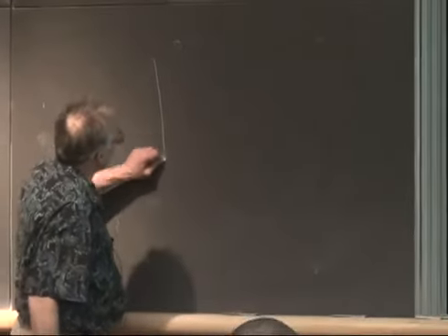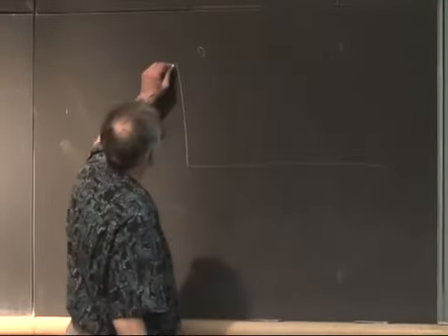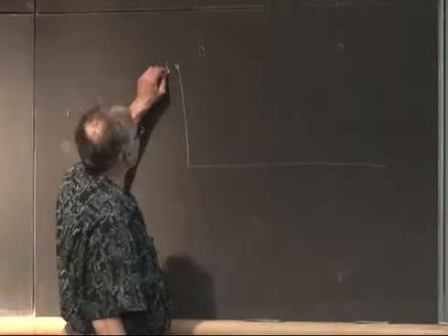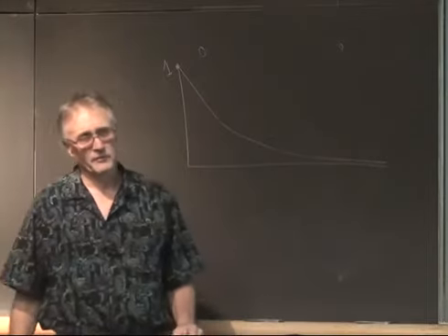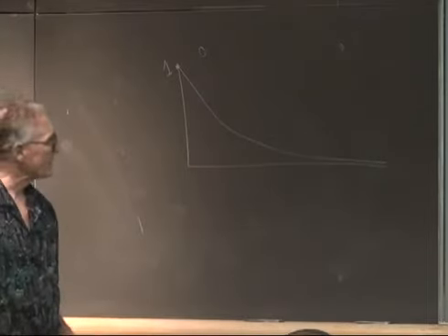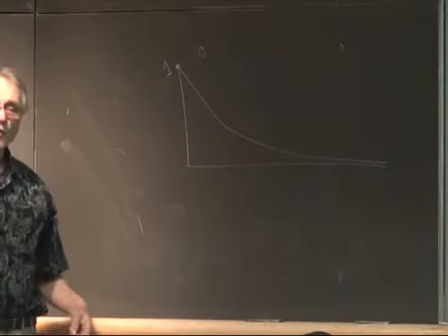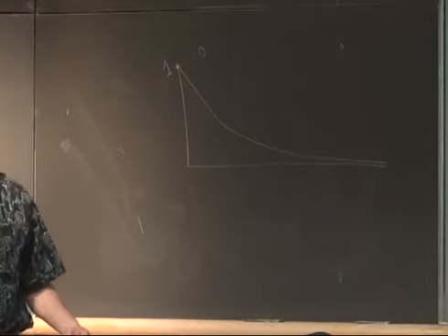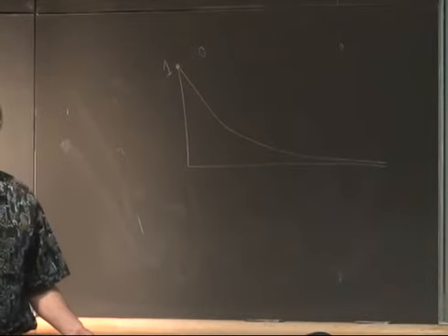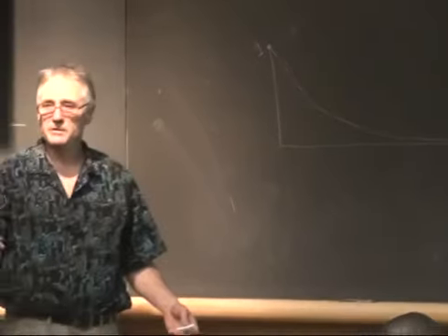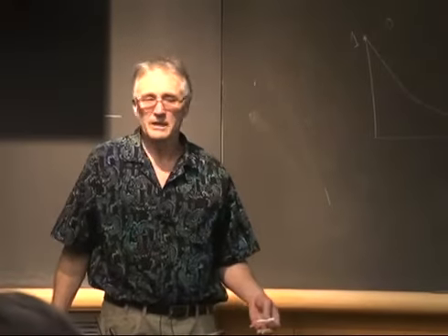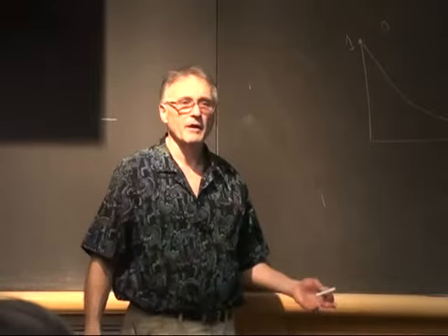So you have an exponential fall starting at some finite value 1 and going on forever. Oh, that's not good for a table. So you have to truncate the table someplace. How far out should you truncate it? How many time constants out should you truncate it? 4? 5? What's e to the minus 5? You got it. Who's got Google open? 0.0067. So it's less than a percent, but not much less than a percent. So 5 time constants is probably enough.